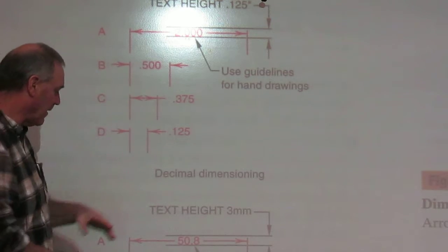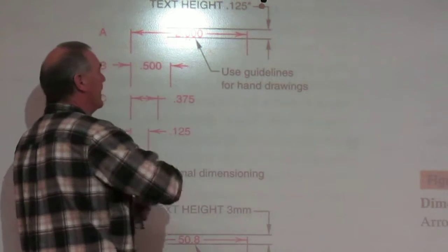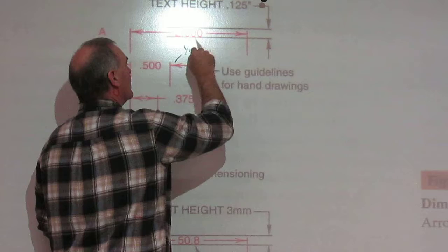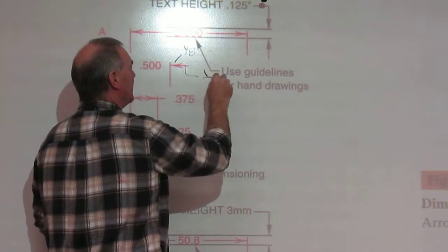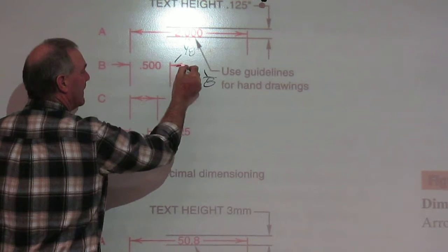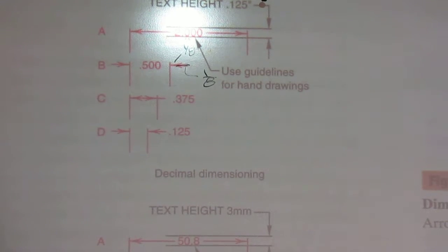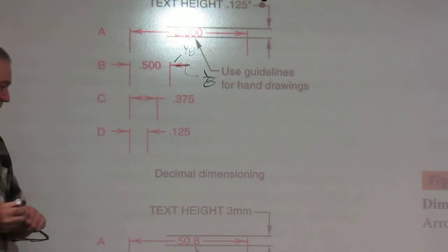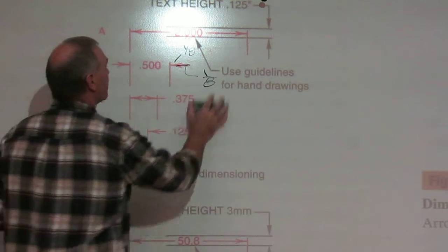Then you pull this out. Now when you're drawing these, remember the arrowhead is an 1/8, right? How big a stretch do you put there? Use the same as your arrow. Put 1/8 of a line on it, and that should be your minimum. Can you go a little bigger than that? Sure, if you have room. But have at least 1/8 on that line right there. So somebody sees it. They shouldn't see just an arrowhead with just a little knob on there. It should be an 1/8 line so that they don't confuse it with something else.